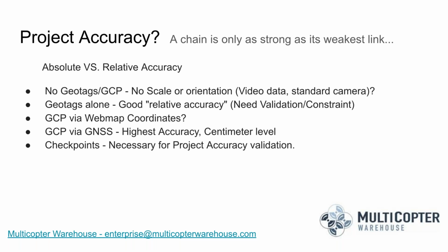But really, you'll get your highest accuracy by establishing ground control points within your project that are being collected with a GNSS, or a Global Navigation Satellite System, essentially just a high-resolution GPS, like survey-grade equipment. That's really the best option.